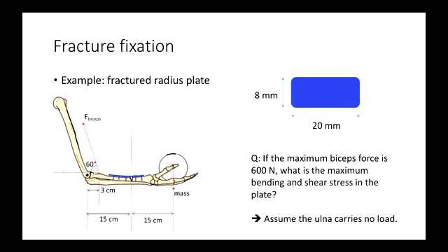I said that the bending moment's like this, 7800 newton millimeters, multiplied by y, where y is the distance from the neutral axis, divided by I. So what that's saying is the bending stress at the centre is 0, and then as you go away from that axis, it increases. So what we find is the stress looks like this.